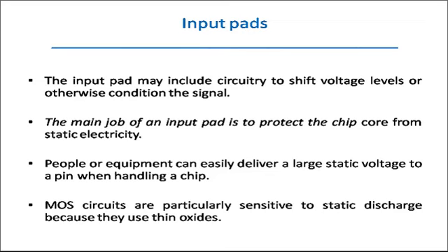The input pad has to protect the chip core from static electricity. People or equipment can easily deliver a large static voltage to the pin when handling the chip. You might remember that at the time of practical, I always say don't touch the IC directly with your hands.